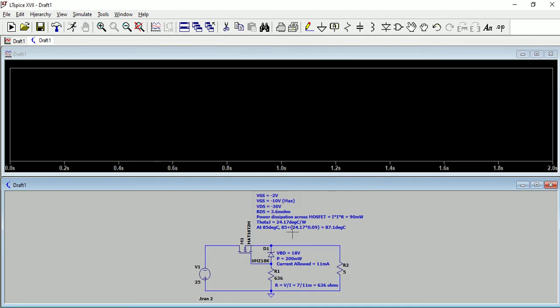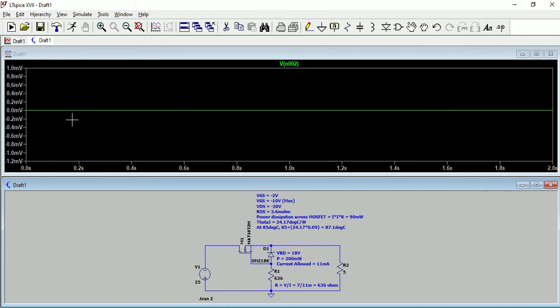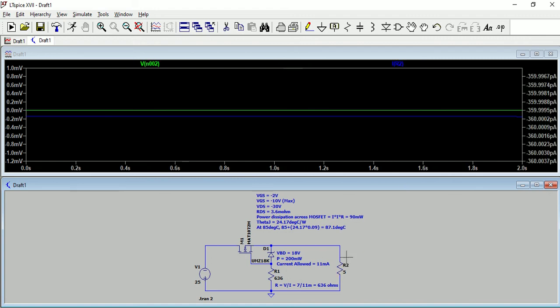And then once we try to simulate, you can see here there is a 0 volt at the output. If you calculate the current, it is in picoamps, so that means there is no flow. So if you connect a reverse 25 volt, the diode is not allowing the current to pass through. Okay, so this is how the